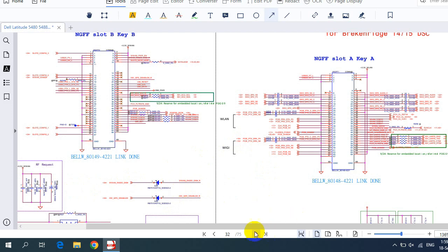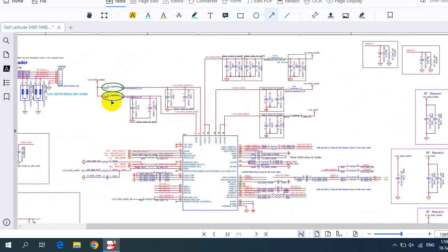Here we have diodes. Here we have inductors. As you can see, we have other inductors over here. That's why I say to you, pay attention. This is an inductor, not a resistor. You can differentiate between them easily. For an inductor, you will find the reference L or PL, but for a resistor you will find R or PR.